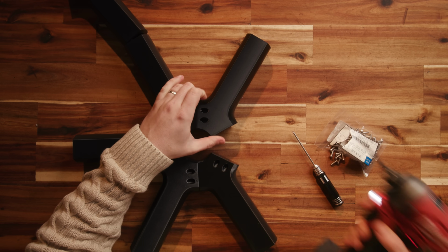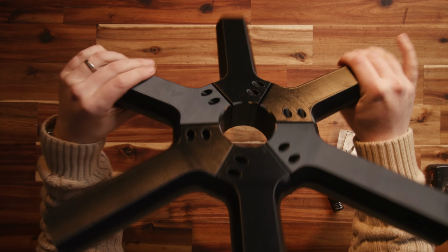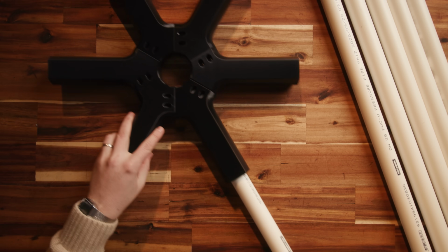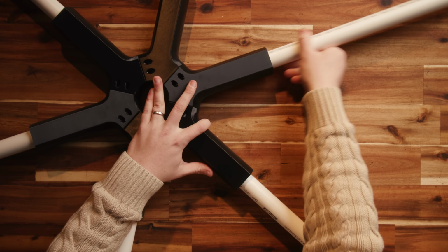These are made of ASA, so they last well in the sun, and because ASA is a pretty tough material, which we're gonna need. This hub makes up the center of our wheel, and these pieces are all identical. They're screwed together with some M4 fasteners and slid over the bottom of the stand. I'm using PVC pipe for the spokes, and they're glued into the hub. This doesn't need to be super strong, but we do need enough strength to cope with the tension from the LED string, so hopefully this does the job.